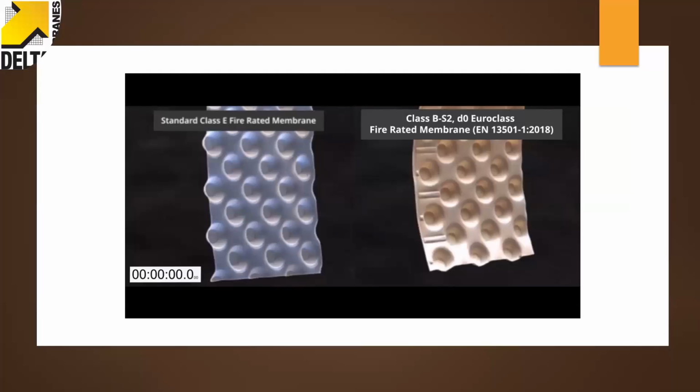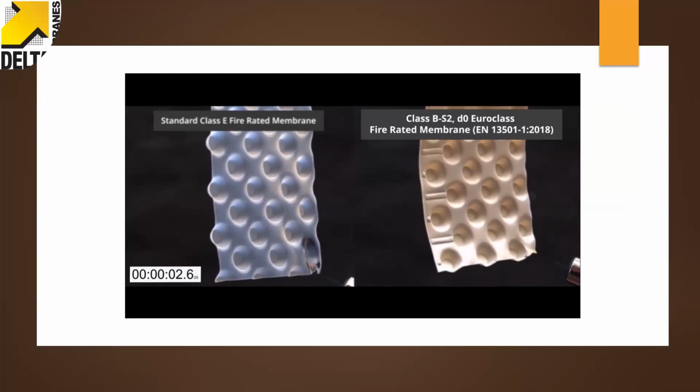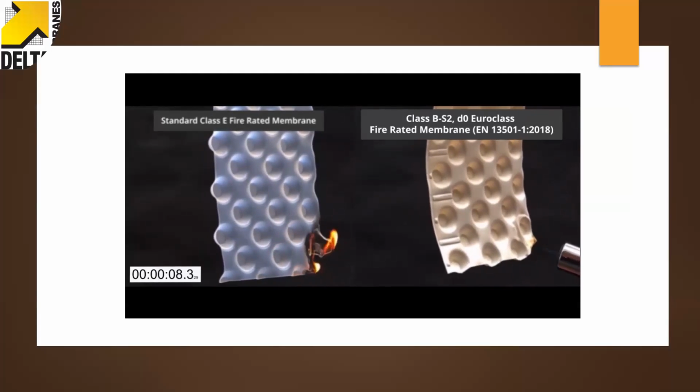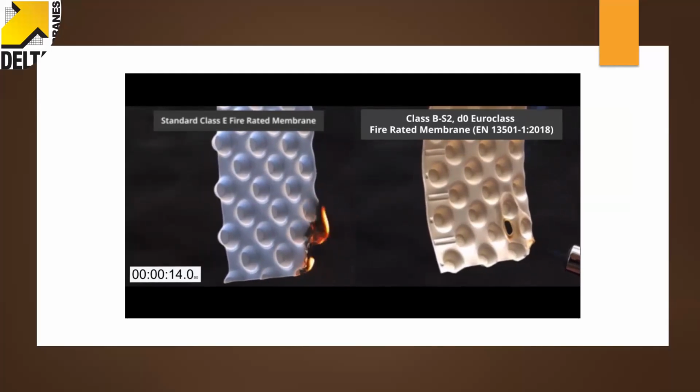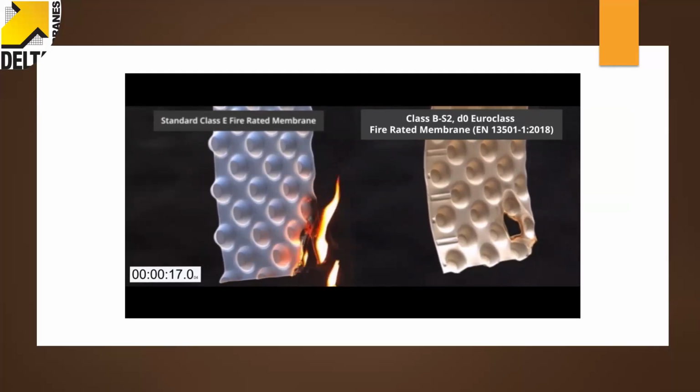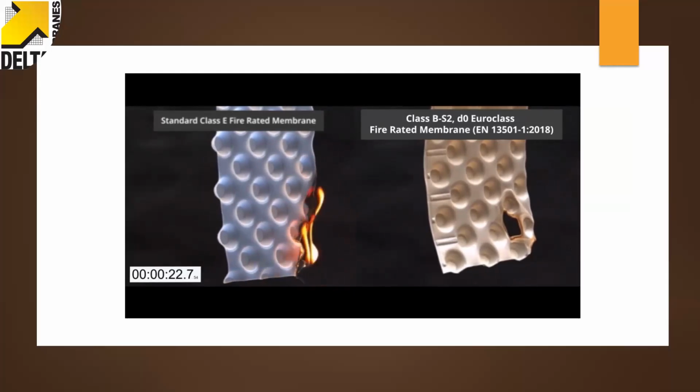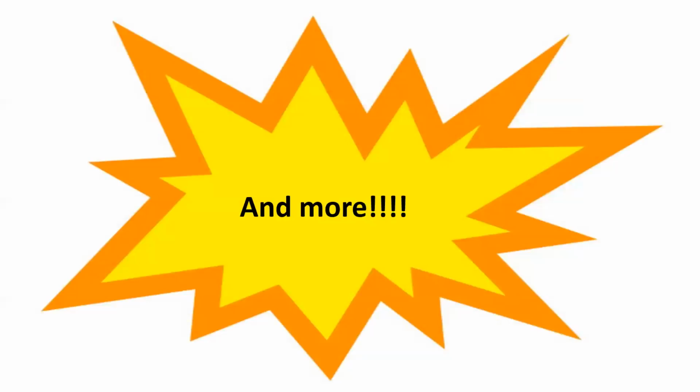And there is some more emphasis on fire safety, as you'd expect with regard to the Grenfell Tower disaster: compartmentalisation in basements, protected routes of escape. In support of that, we've actually developed a fire retardant membrane. On the left, you can see a standard HDPE cavity drainage membrane, which is flammable and supports the propagation of toxic fumes and whatnot. And on the right, you can see Delta MS Fire cavity drainage membrane, which just melts basically, so it doesn't actually burst into flames. So that's a unique product that Delta have as well.